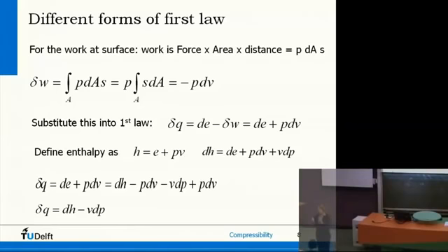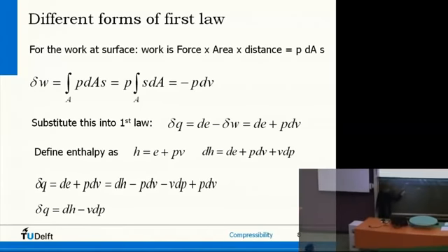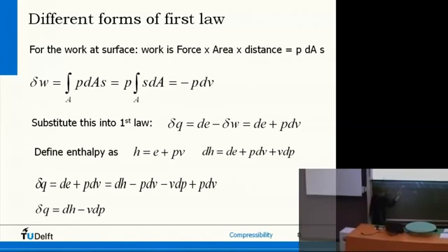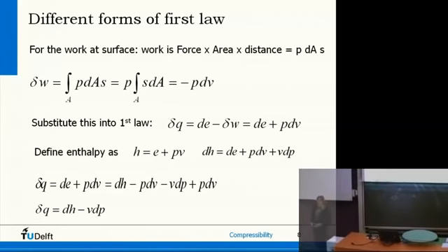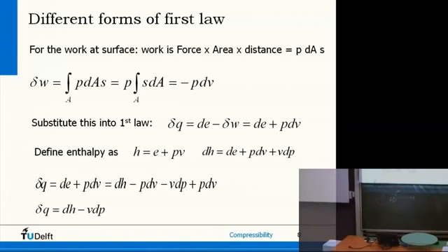So in normal direction, we have a P on this small blob. And the work done at the boundary, so this del W, so the small change in work, is due to the pressure. If there's a high pressure outside, a lower pressure inside, the boundary will be pushed inside, like this. And then the force actually doing this is pressure times area, so P times dA.